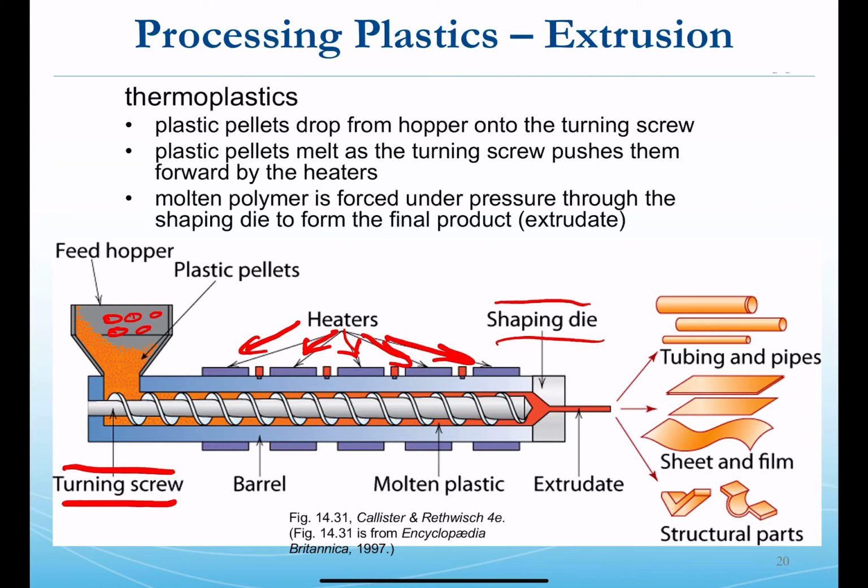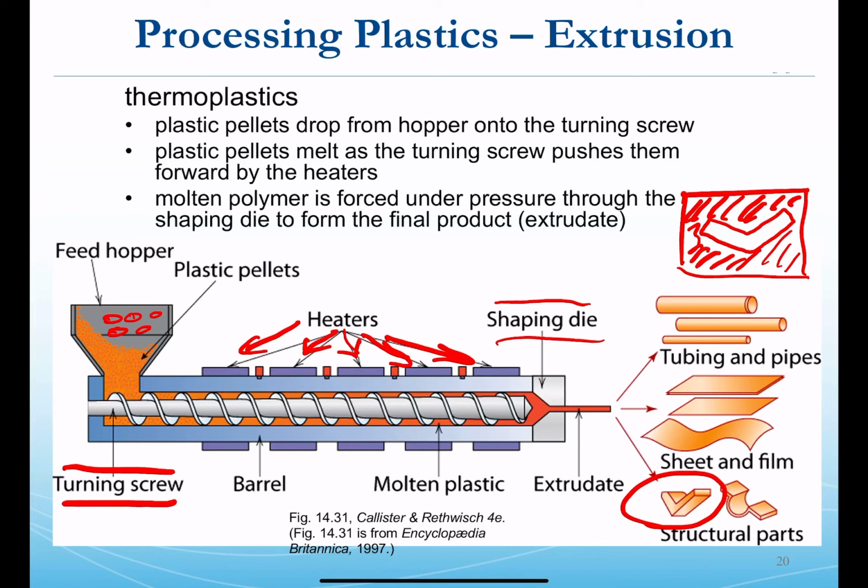So the orifice there, the opening of this die, dictates what shape the extrudate, the material coming out, takes. So if you imagine that die, looking straight onto it, had an opening that looked like one of these V structures, where all this is metal, and shown in white is the pathway into the barrel where obviously molten plastic extrudes from, you would get an extension of material coming out of that die in the form of this V-shaped structure.